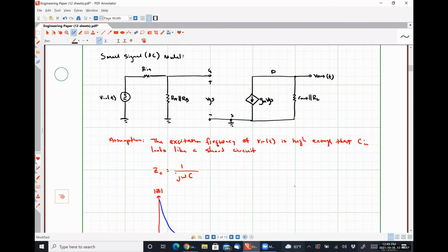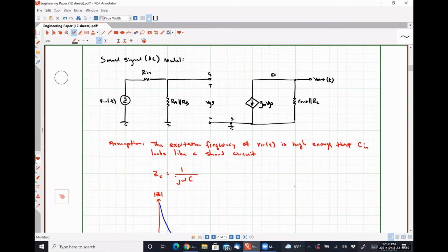I'm going to scroll up here. We're going to talk now about how to figure out what our small signal voltage VG is, our small signal voltage VD is, VS is, and all that kind of good stuff based on the layout of this circuit, because it's those small signal parameters, specifically the VGS, how it relates to Vn and how it relates to V out, that tells us how this works as an amplifier.